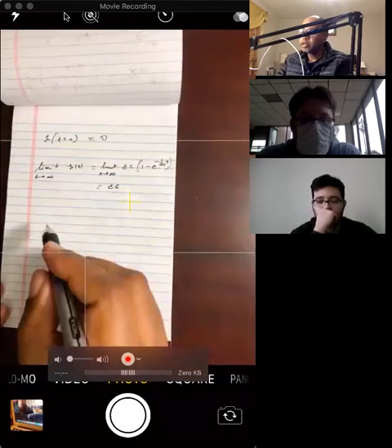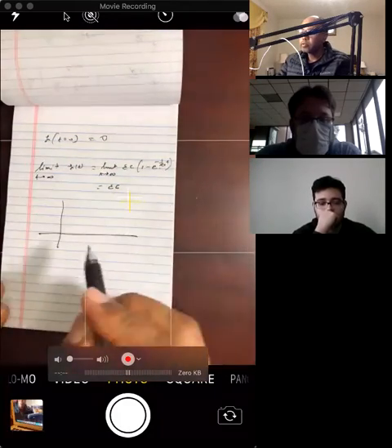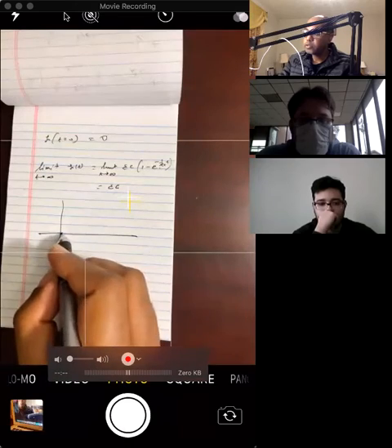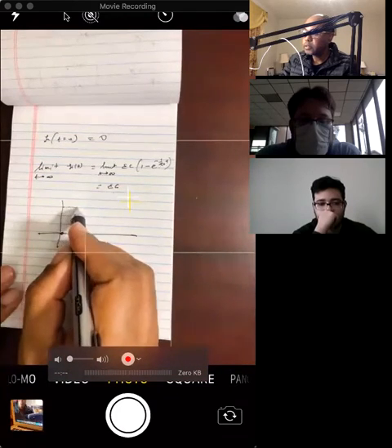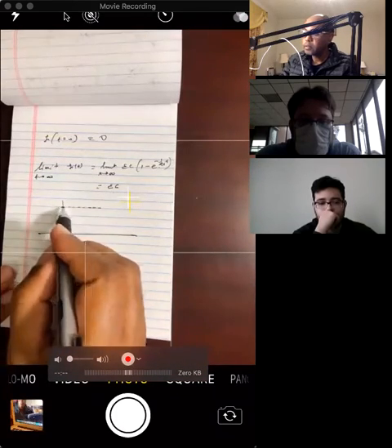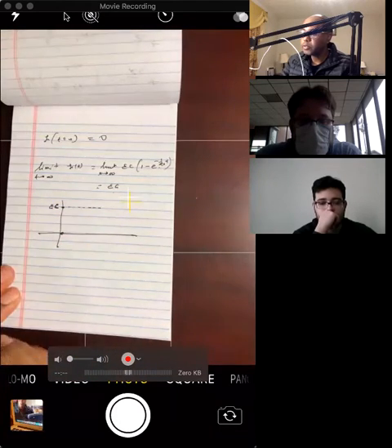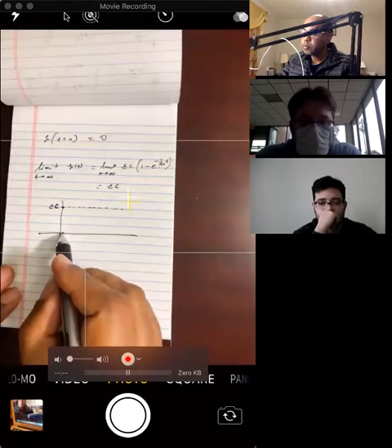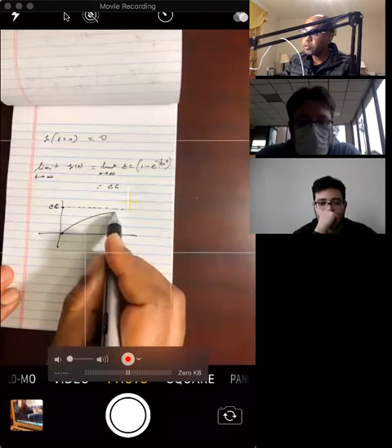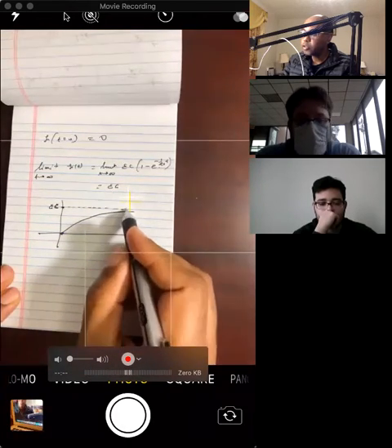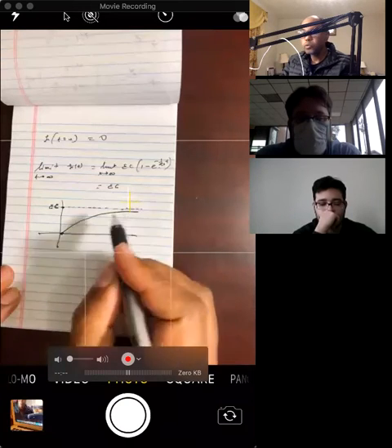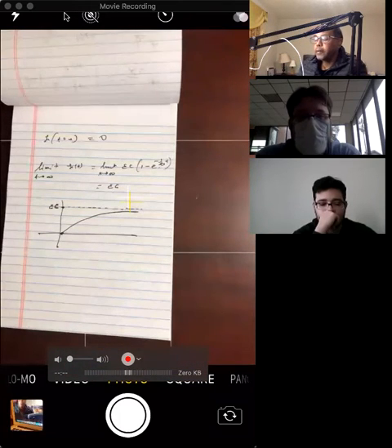So now we can plot the graph. It's an exponential function. We just saw that at t equals 0 it is 0, and this is the EMF times the capacitance of the capacitor. So it approaches this value as we go to infinity. The charge builds up slowly to this value. So that's how the charge increases in this circuit.